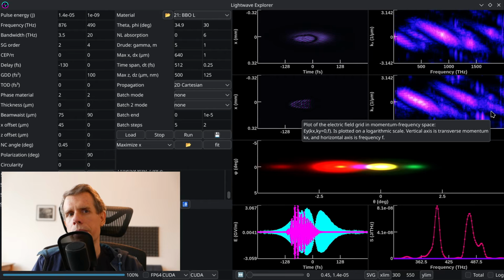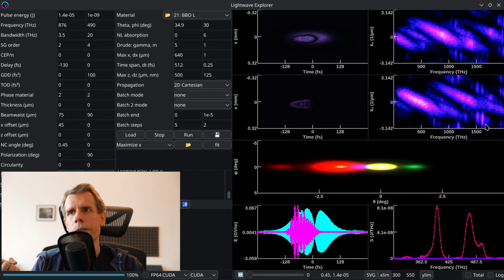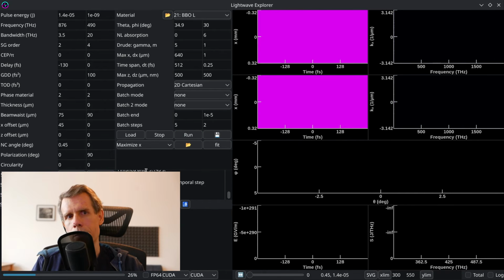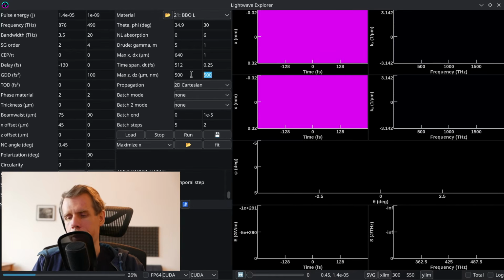And these high frequency components are the most difficult things to include on the grid because they have the largest value of the K vector. High values of K vector are typically the most difficult to include in the numerical grid. Now you'll see if I go back up to this value where we started for the step size, the simulation is going to fail completely. So if I say run, it will just say that it detected not a number on the grid. And that's because these higher frequency components are very unstable. So you have to be cautious if you're including them on your grid.